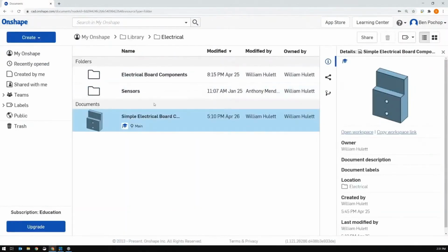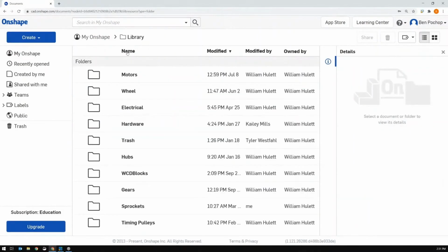By having it all in different documents, you're going to run into processing slowdowns. It is not the best method that we've seen, and it has kind of caused our assemblies to chug. If you have your links or your link documents and your versions, I think Onshape posted an update recently that said that's the best practice, and you're going to see better performance.